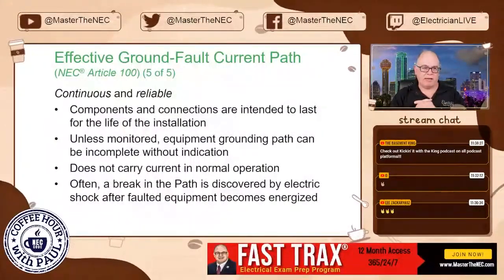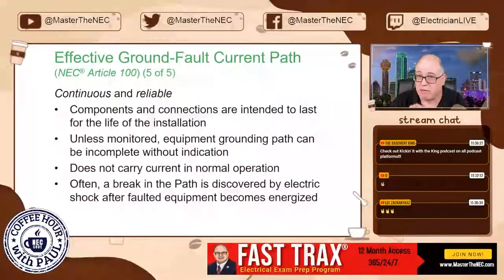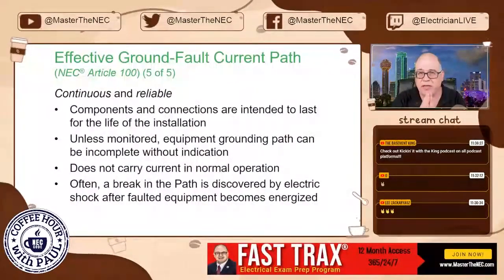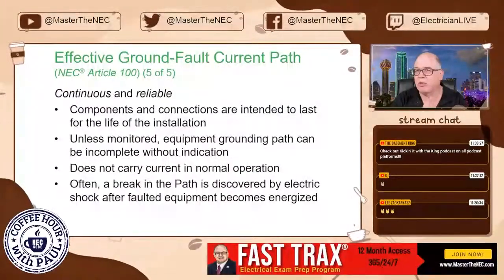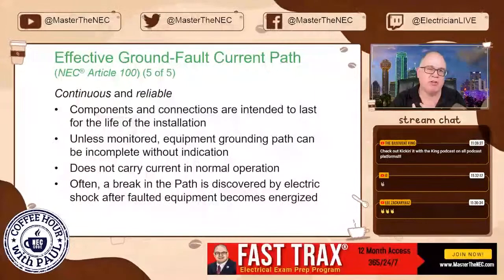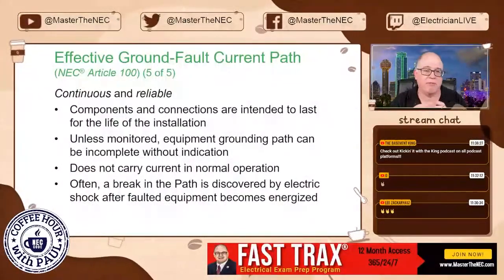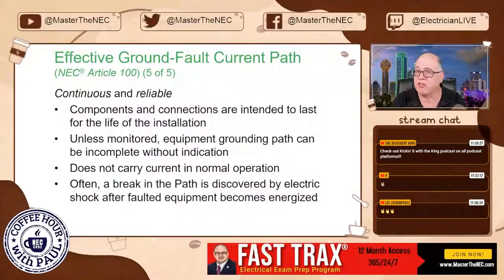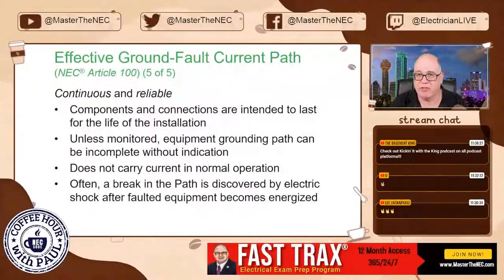Again, when we install an effective ground fault current path, the equipment grounding conductors, here's something you need to remember. We're not doing this temporarily. So when you make all those connections and you torque them and you do everything, remember, you're making this connection for the life of the installation.